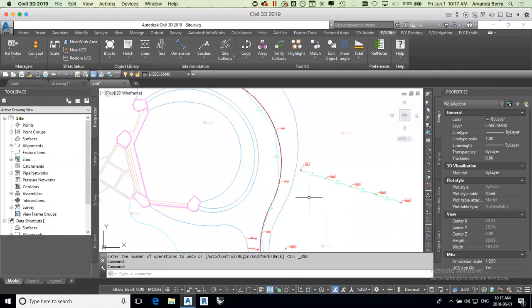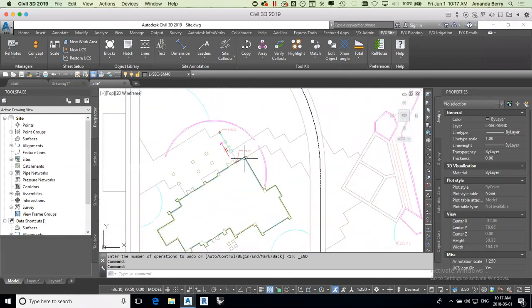Again, these solutions are easy, and for many designs, they're enough. Really think before you start about which solution would be better for you. For a small plaza like this, or a simple swale grading like this, civil is honestly overkill because you probably aren't going to need cut and fill, and you'll spend way too much time setting it up without enough time benefit.